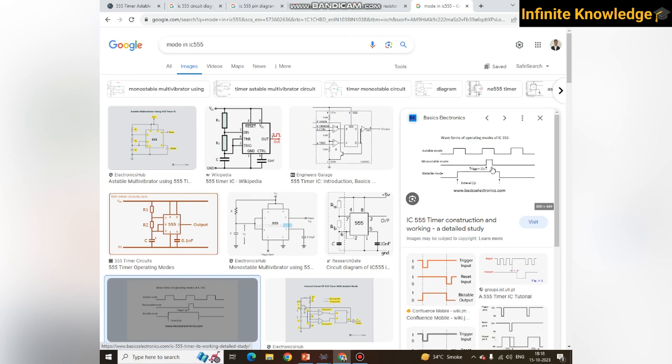Here you can see that for a very precise time it remains high and then goes back to 0. No signal is required to go back to 0. It goes back automatically, according to some capacitor and resistance values, and that defines this state.